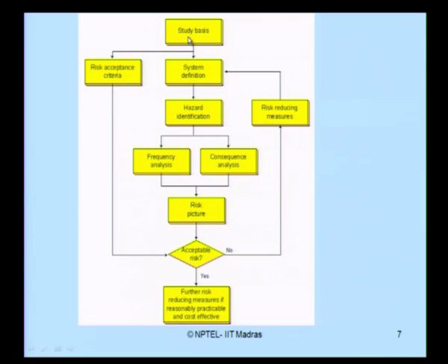So, identify the risk acceptable for the case study which you are discussing. If that level of risk is acceptable to you, then further carry out risk reducing measures if reasonably practical and cost effective. If the risk acceptance criteria are not met, then the question comes, how do you do a QRA, how do you actually do the risk assessment using quantitative tools.